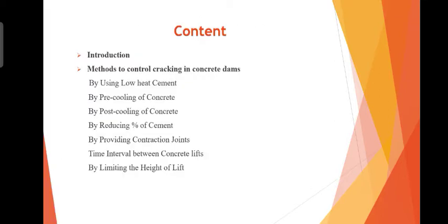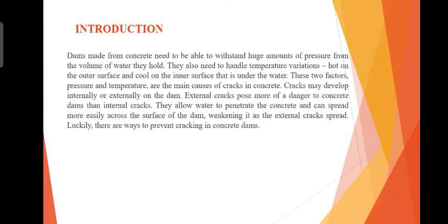The content of my presentation is the introduction and different methods to control cracking in concrete dams. First is using low heat cement, then pre-cooling of concrete, post-cooling of concrete, reducing the percentage of cement, providing contraction joints, time interval between concrete lifts, and limiting the height of lifts. First of all, the introduction about my topic.